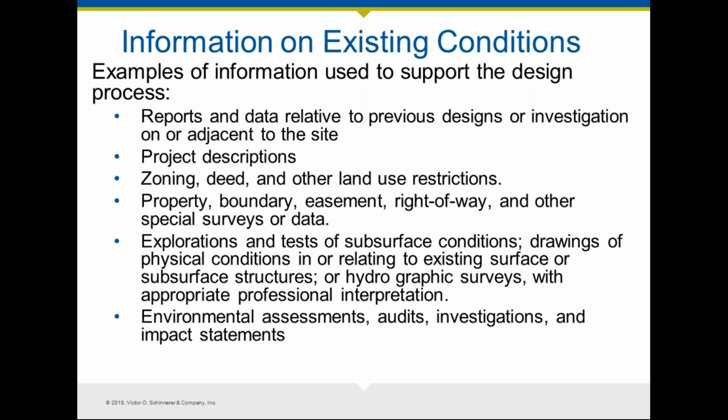Data relative to previous designs or investigations on or adjacent to the site. It's not unusual for the owner to have started the process of designing something for a particular site earlier and gone through developing information, or it could be the previous owner of a particular site that has engaged these surveys and geotechnical investigations. If that is indeed still reliable, you may be able to rely on that. Project description, zoning, deed, and other land use restrictions.